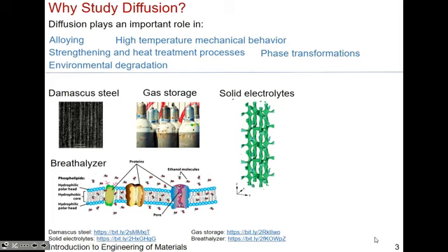There wasn't really a formalism, but it was a good example of diffusion. So basically the carbon in this pile of ashy wood was carburizing the steel, the iron rod, and then making it stronger, iron carbon, right? So that was a good example of how to strengthen material through the process of diffusing carbon.